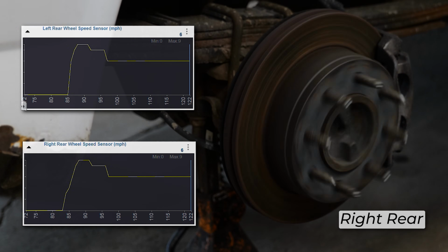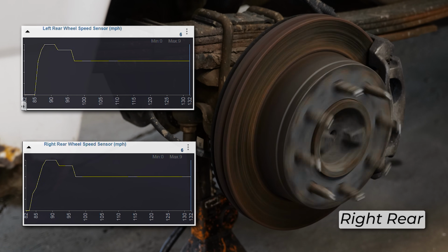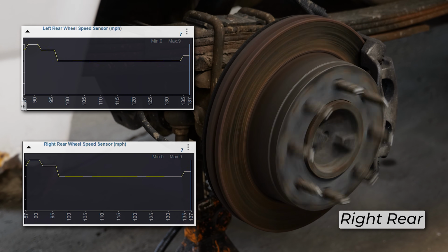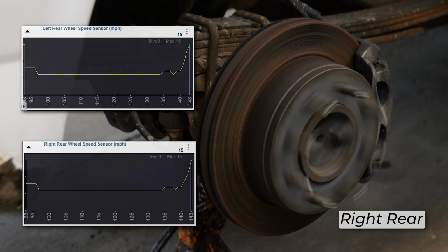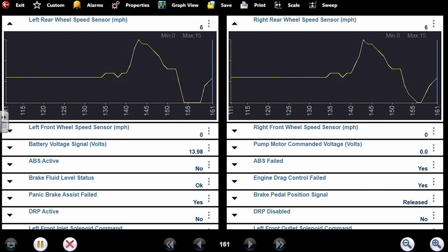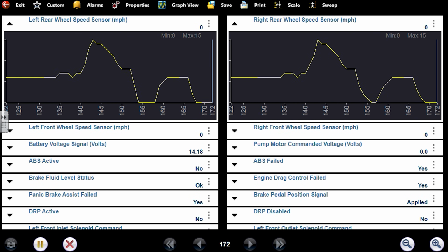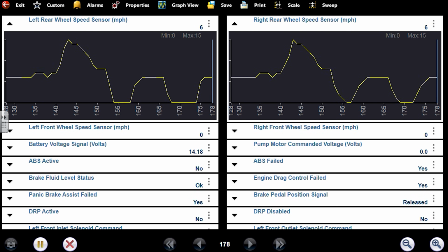Now, we may not have the same speed for both if I rev it up a little bit, just because the wheels are off the ground and this is an open differential. Looks pretty even right there. But yeah, I mean, we got signals on both. I'm on the brakes, wheels are stopped, off the brakes.